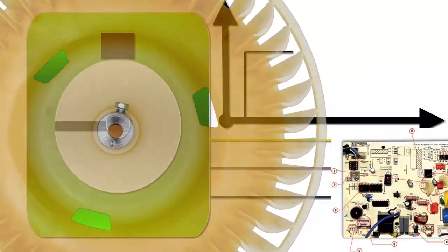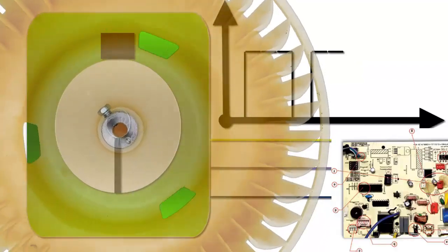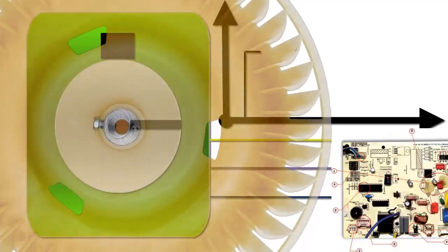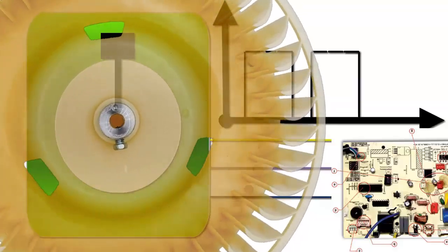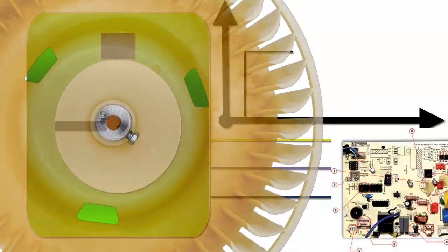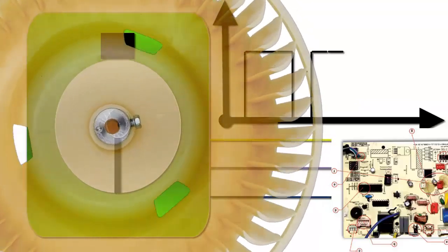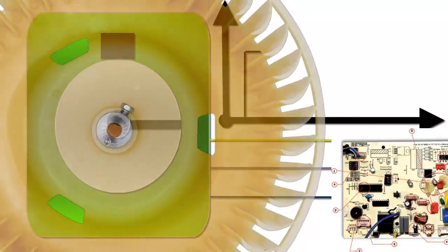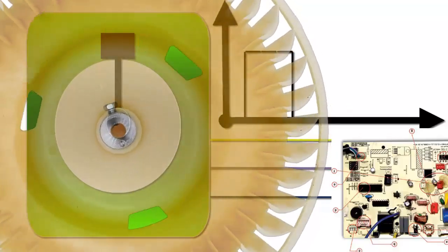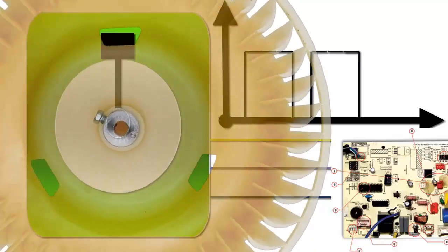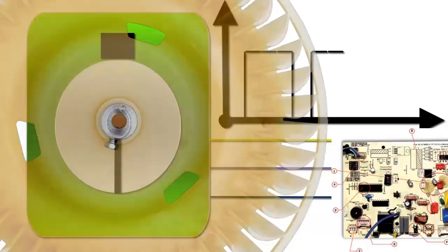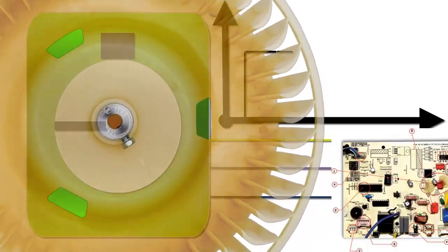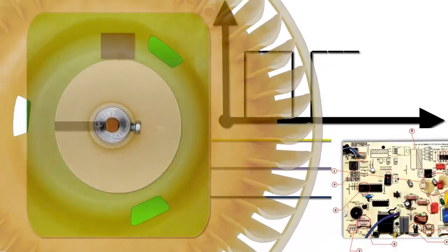Common error codes. The H6 code is used by several brands to indicate failures in the indoor unit fan. The E6 or EF code for the TCL brand indicates problems in the indoor unit fan motor. The E8 code may indicate problems in the indoor unit fan in brands such as Midea, Akai, and Sharp.